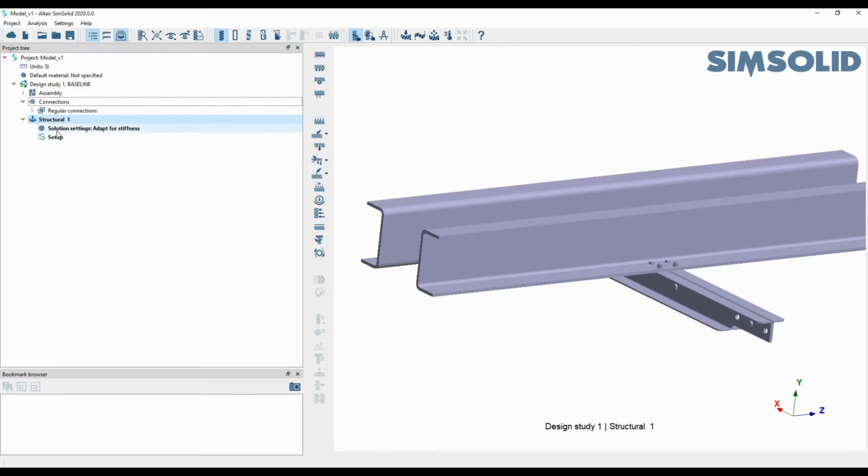Now you'll see the moment we specify structural linear, it comes up with a new section within your design study, and you'll see a whole new plethora of buttons for the secondary toolbar. You'll see within this section here, so this top area, the top four icons, they represent your different constraints. So you can specify an immovable constraint, a slider support, a hinge support. Obviously, an immovable constraint means it's constrained in all degrees of freedom, so it cannot translate or rotate in X, Y, Z. If you're specifying a slider support, that means it's free to translate in 1 degree of freedom. And obviously if you specify a hinge support, then you're enabling it to rotate around 1 degree of freedom as well.